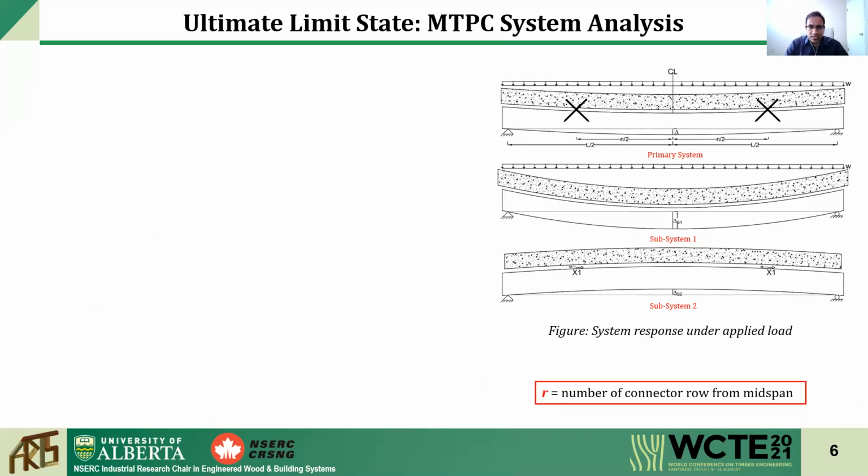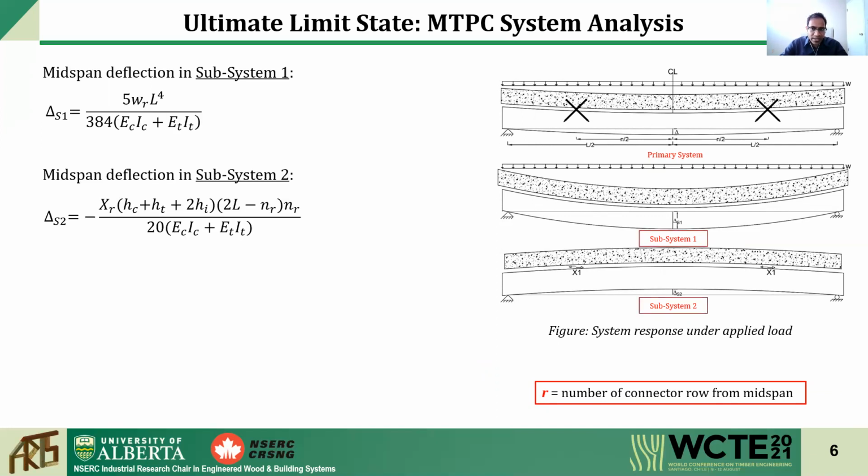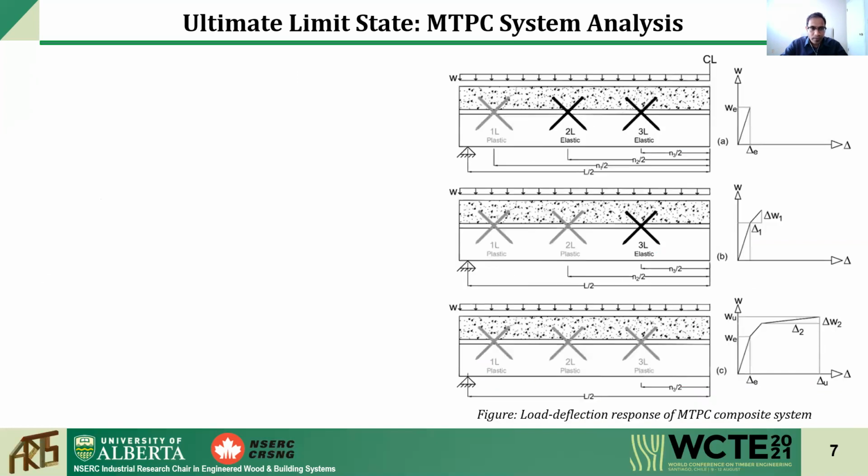The midspan deflection for the two subsystems can simultaneously be calculated from these two equations. And after adding them based on the superposition method, we can calculate the total midspan deflection for the loads. The nonlinear load deflection response of the MTPC composite system can be generated by calculating the load and corresponding deflection after yielding of each connector.